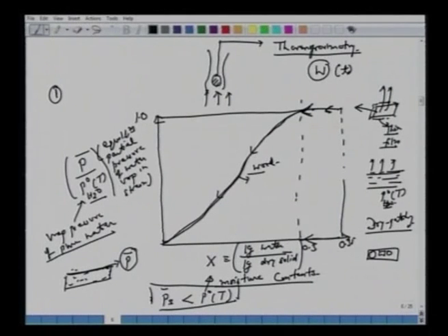All right. So it decreases, so it's going to decrease. You will expect that when it reaches a certain level of partial pressure in the atmosphere, so now you're drying with air, this air partial pressure, moisture partial pressure, moisture content in this is fixed. So let's say this value is 0.6. So are we plotting P bar over P0T? You should recall from some other class, that's nothing but relative humidity, or relative saturation.